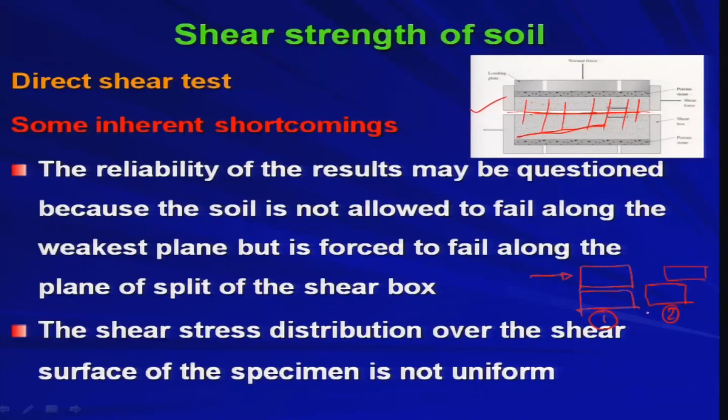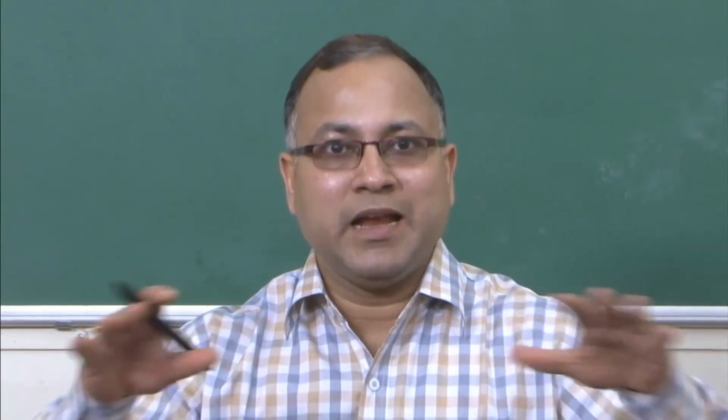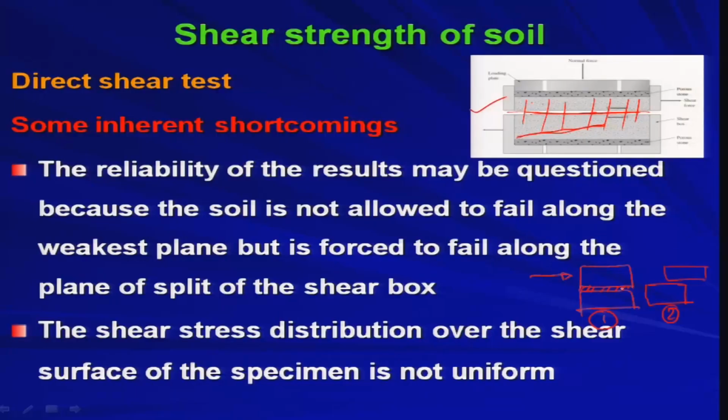So, you are getting this kind of situation at each and every point. At the initial stage, when you apply the shear stress, whatever pushing you are applying to the soil will be acting over this area. So the total area will be participating in the resistance of the shear stress. However, as the test progresses, you will be getting only this much area taking care of the externally applied shear force.